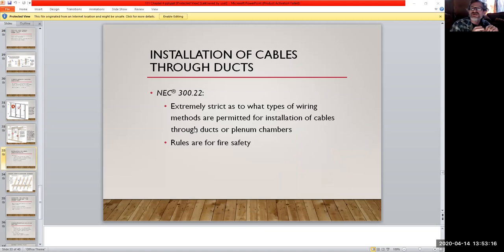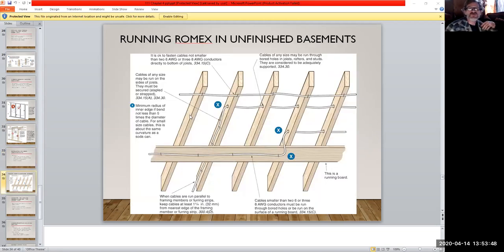And then they have rules on ducting, that type of thing. You have to be careful when wiring, because ducts, again, are metal. So basically you have to make sure that at no point are you going to have a situation where you end up energizing the ductway, and we're talking AC heating ducts and that type of thing. So if you do have to fasten onto the ductwork, you have to follow some rules just to be sure that there's no way that you're going to end up energizing the ductway at all.